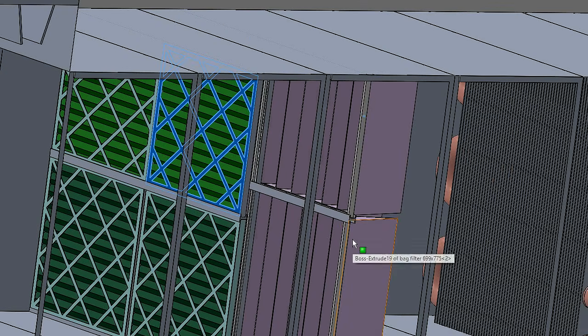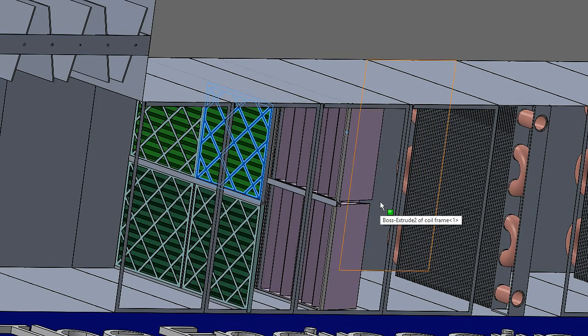And there is a surprising amount of dirt and just muck that comes in with the air, and you want to get rid of that and filter it out before it hits the coils, and also before it goes into your fan, is sucked in by the motor for the cooling, and is also pushed out onto the floors for the occupants, for the tenants, the office workers. They're going to be breathing this air in, so it's important that that air is cleaned and is conditioned in a correct manner. So the first line it will go through is the panel filter,